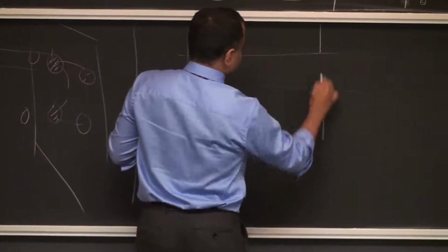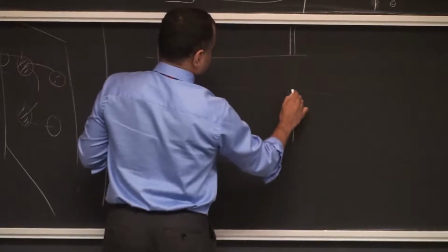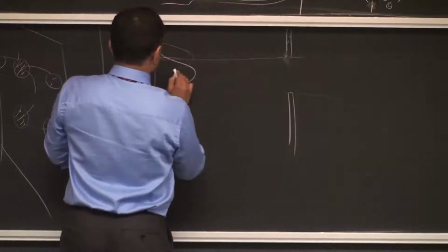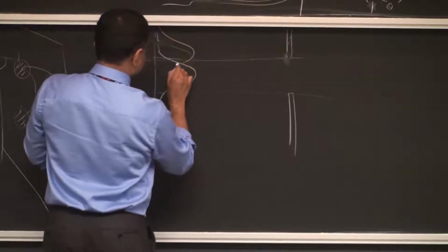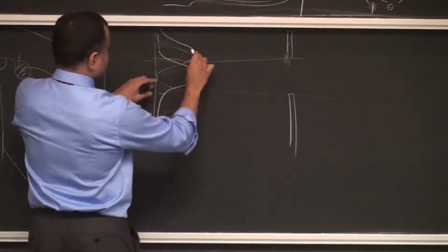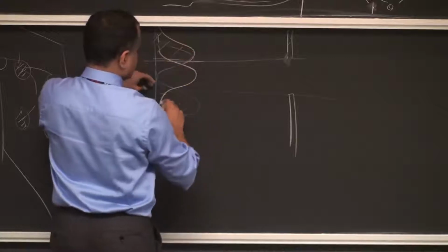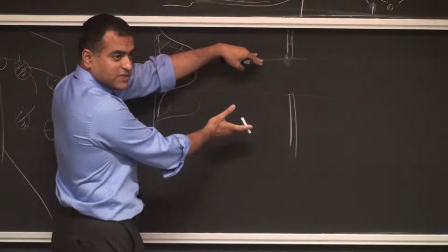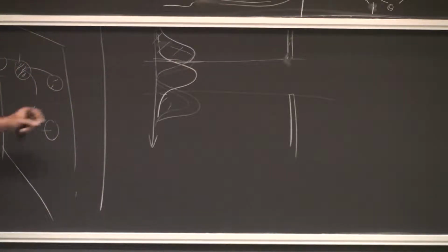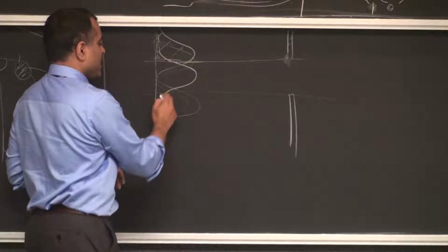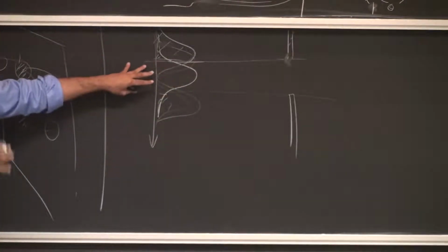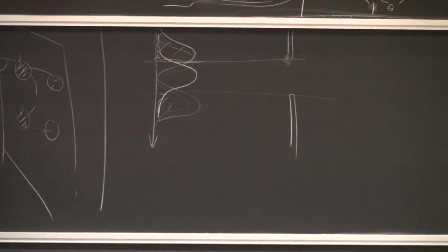So you can put in essentially a reflector or something of that sort here. I think I kind of didn't draw it right, but it will look something like that. So essentially, you can cut off these two beams by just doing that. It's a physical filter which filters out the central beam, 0-0 mode, and rejects the other mode physically. Obviously, you will also lose a little bit of that, but then there's a lot of other engineering that goes into fixing those issues. Does that make sense? This is a physical filtering. If you've done electrical engineering courses, you do all this in frequency domain.